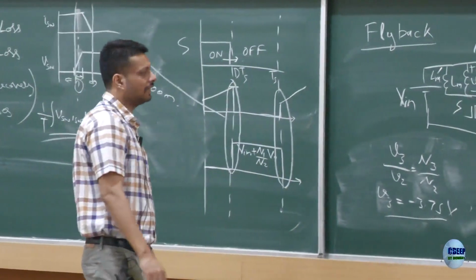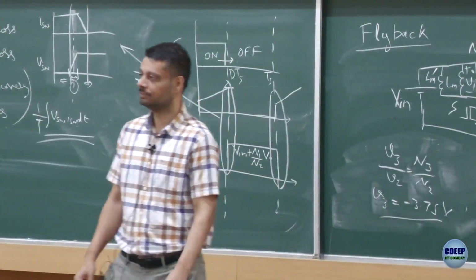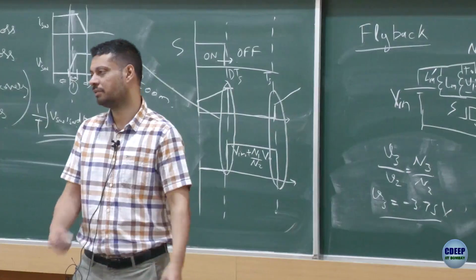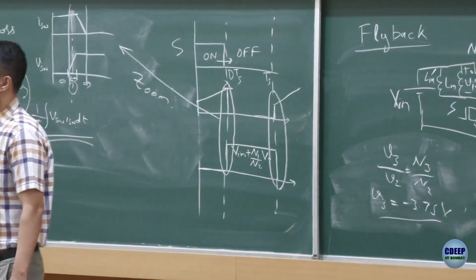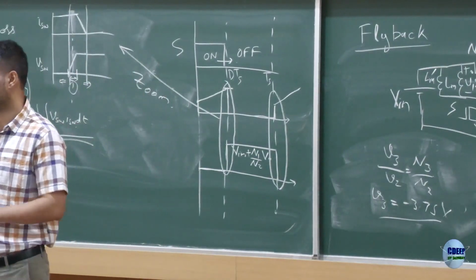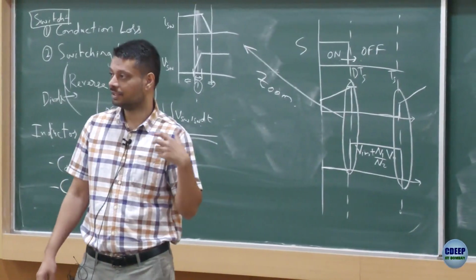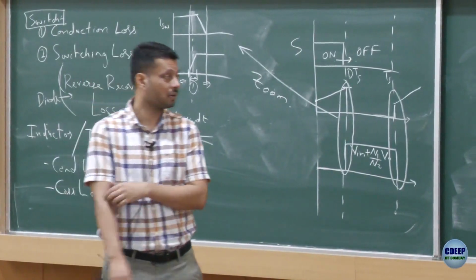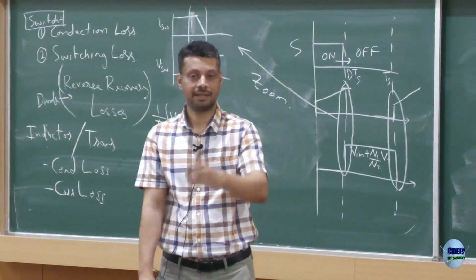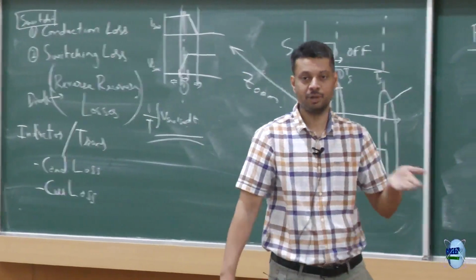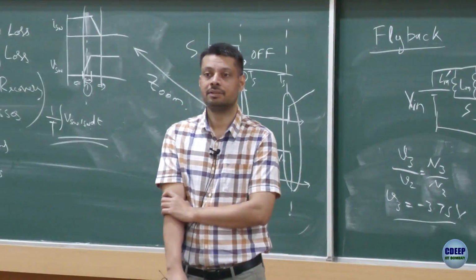Saturation of the inductor or transformer, yeah, it will saturate, and the transformer will saturate in our next topology also. So I won't put it for now because you would still have to live with the transformer, right? You cannot avoid it. The other circuit may also saturate at high voltage. It is very difficult to say clearly unless we see the next circuit whether in that particular aspect it is bad or not. Anything else? Any other points? This guy also said that, but that's only if you have an output voltage, so let's not put it as a negative thing.